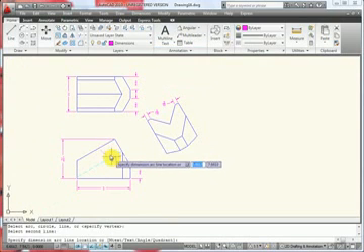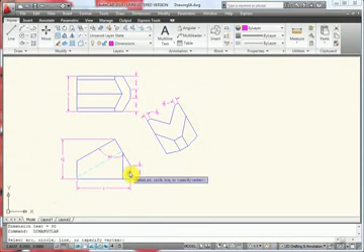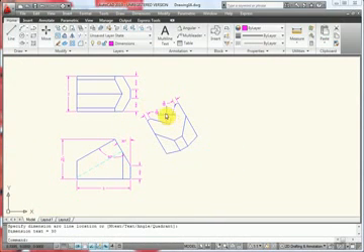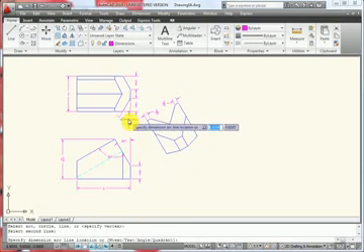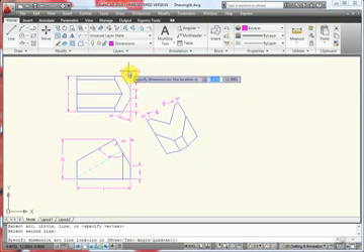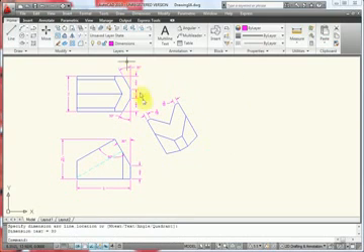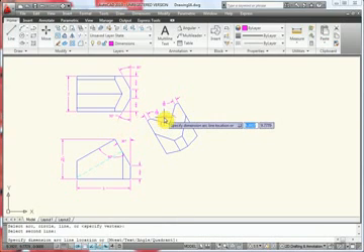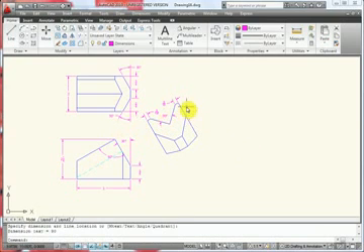I'm going to angle right here, our 30 degrees back, here, 30 degrees here. Make sure you draw the angle in the right direction, that way you can reference the right angle, and the 90 degrees here. And there you have it, your first auxiliary view.